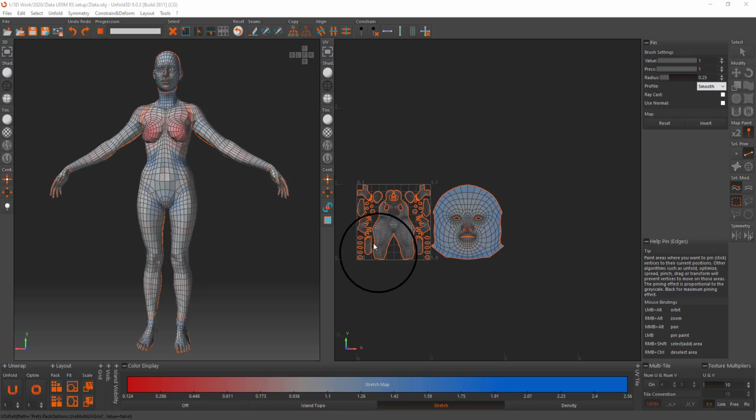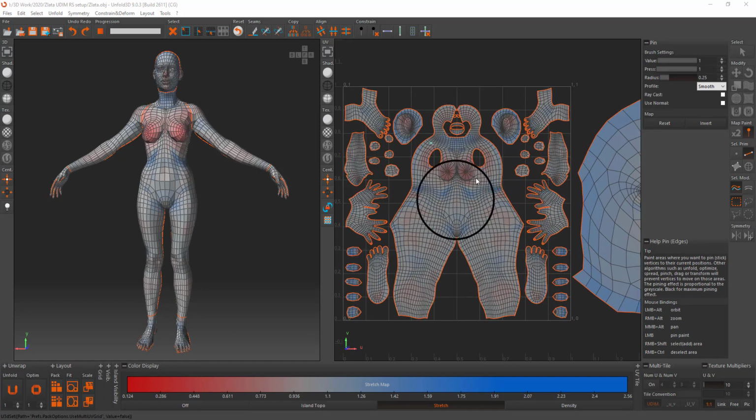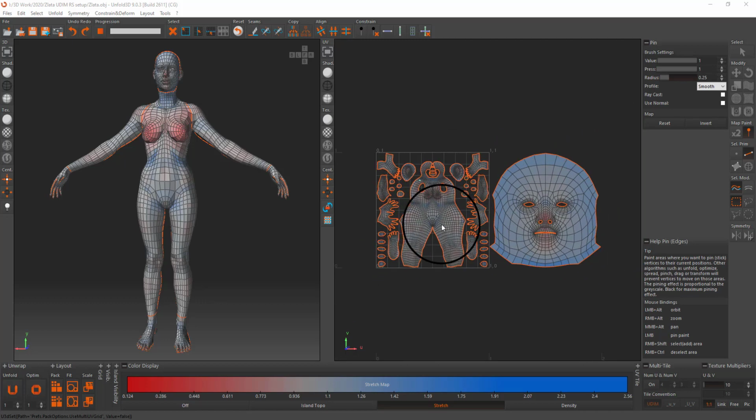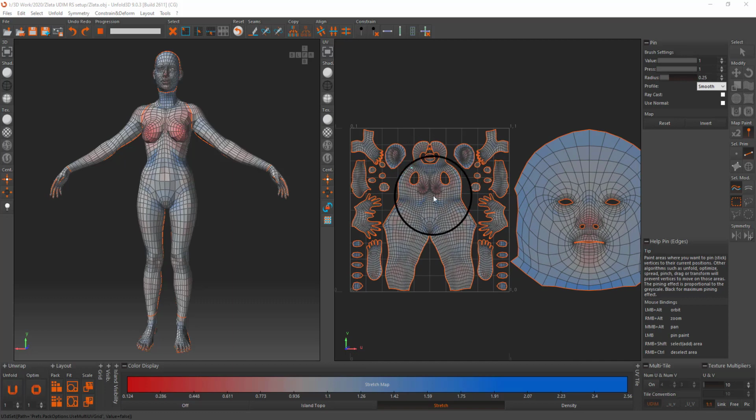In the right hand side of the screen, I want to draw your attention to this box here. This box unifies the area in which the UVs fall within. Now inside Cinema 4D you will see a similar thing. You'll see this grid box, and all your UVs for your 3D model must fit within this grid box. Now when it comes to working with UDIMs, you can have multiple grid boxes, or as they're called, tiles.